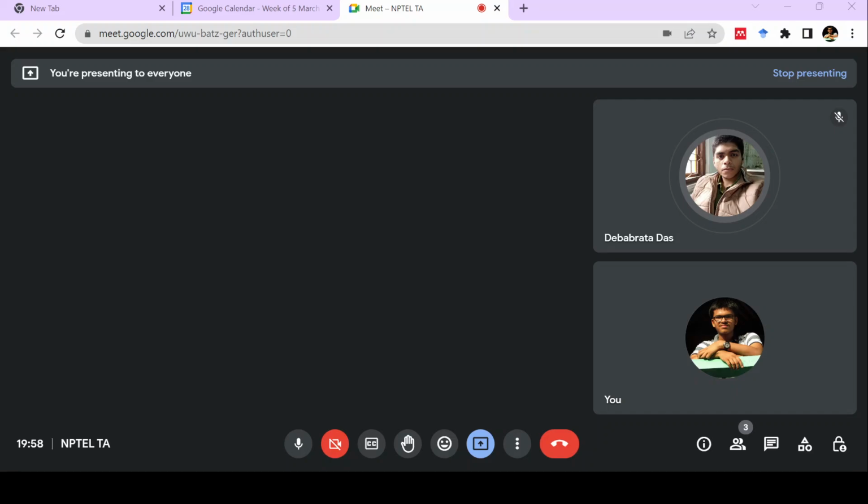Now we are considering this point because we want to make sure that the moment applied by this FB will be zero. That we can make sure only if we are measuring the moments from the point B. So from point B, the moment due to FB is zero.